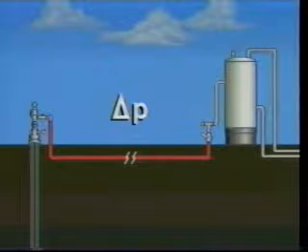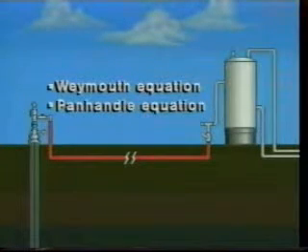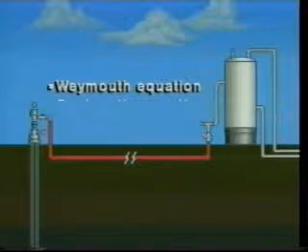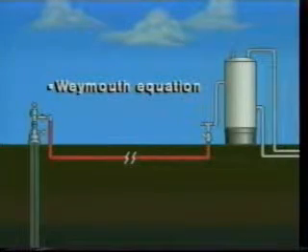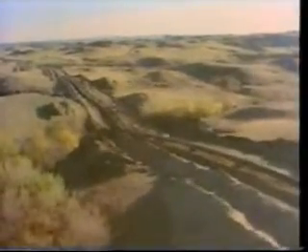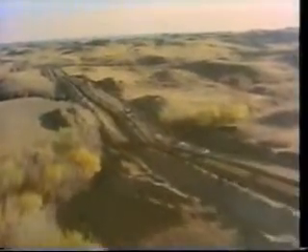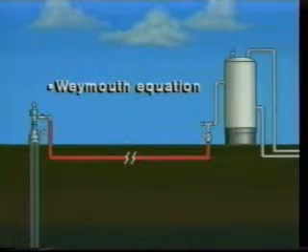Calculations for determining pressure drop caused by friction in gas lines, where gas flows usually as a single phase, commonly employ the Weymouth equation or the Panhandle equation. The Weymouth equation is generally used when pipe ID is less than 12 inches and pressure is less than 500 psia. The Panhandle equation has proven to be more appropriate in larger pipes and with greater pressures. Let's look more closely at the Weymouth equation, which has greater application in the design of flow lines.